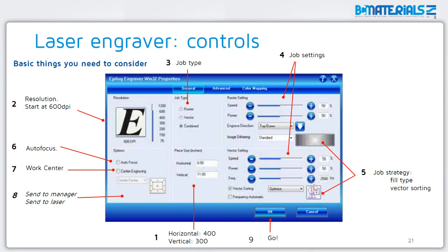And then you define the strategy of your cut. So you have two options. You can either optimize, which means that the driver will calculate the trajectory that minimizes the duration of the work. Or you can select inside out, which means that the work will be done by cutting the inner structures first and cutting the outer contour last. Okay, I recommend you choose inside out by default.